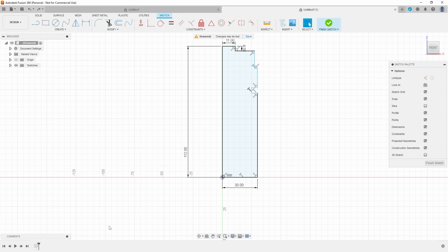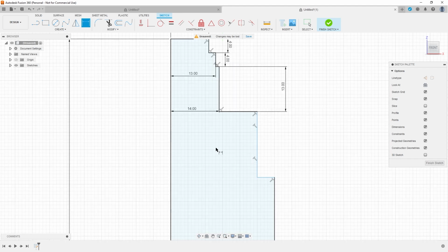Okay, working from the top down, let's get the next dimension. We have got 26 millimeters. Now, some cool things you can do with dimensions. A dimension here and here. I can type in 26 divided by 2. I can put a formula in here and it will snap into place. So it's really handy if, like me, you know the formula to get what you need. You can't necessarily drive math. This is 28, 13. So that's our cap.